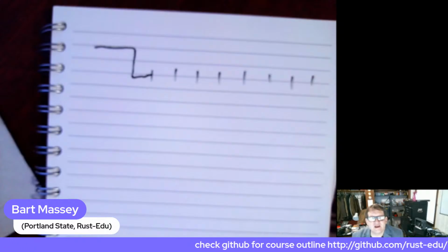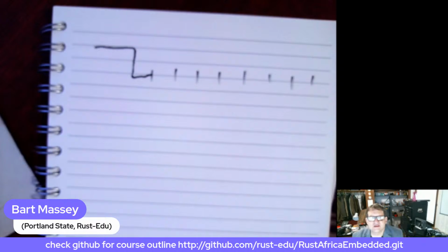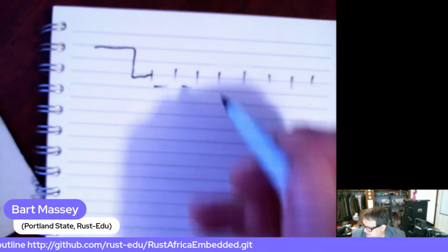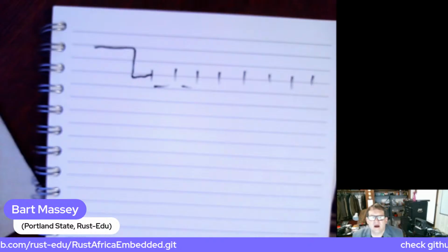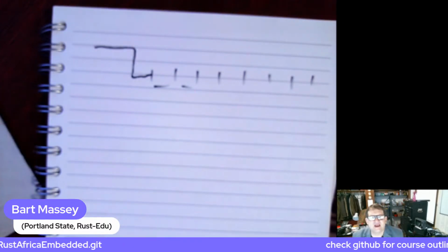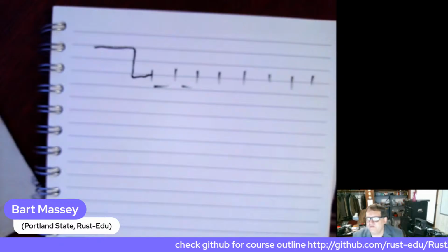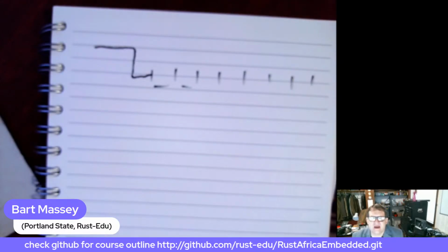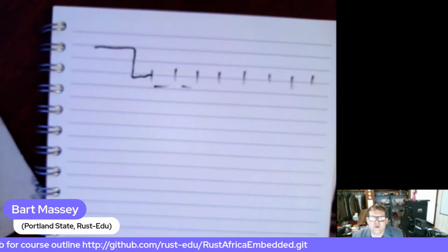So we just send a byte down the wire as a series of high and low pulses. This bit time is called the baud rate because reasons. Our serial port, on the micro:bit, is capable of going very, very fast. You can send at a notional rate of almost 1 million bits per second.